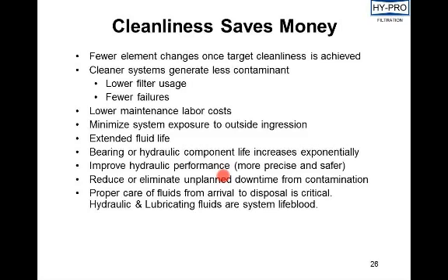Well, the difference is the flow rate change. As we perform a DFE test, we are rapidly changing flow. We can do it as quickly as 0.1 seconds, going from a flow rate of 25% of max flow to max flow. So it's very fast, and the shock and challenge to the filter element is very dramatic. It can be, depending on how we set the test up. But again, it's just a more real-world way of testing these filter elements in a way that they're really used on a hydraulic system.